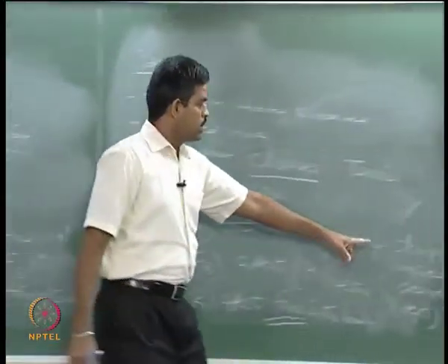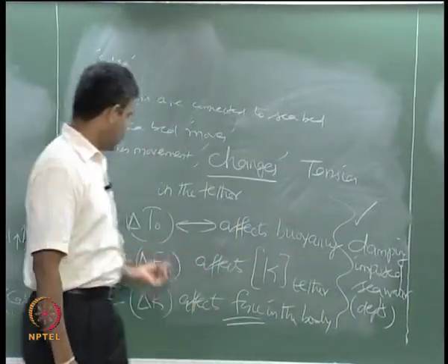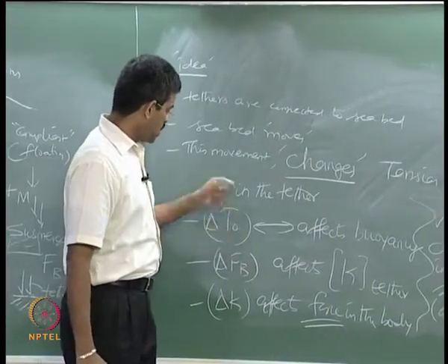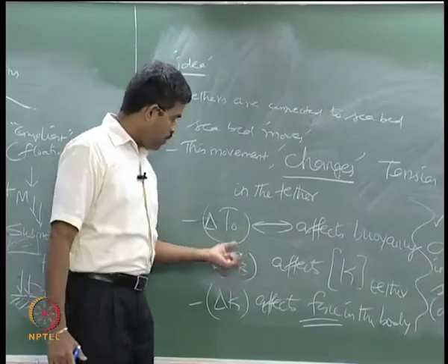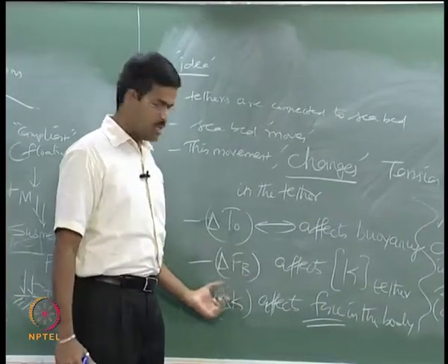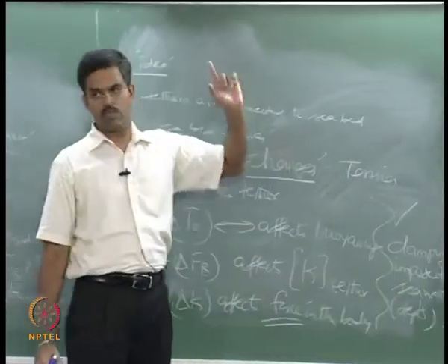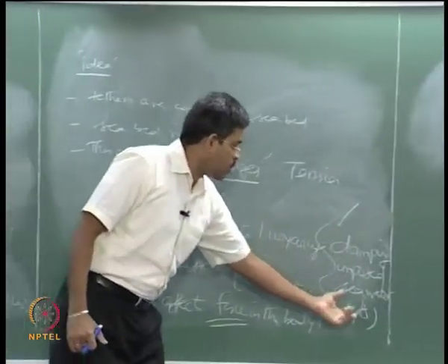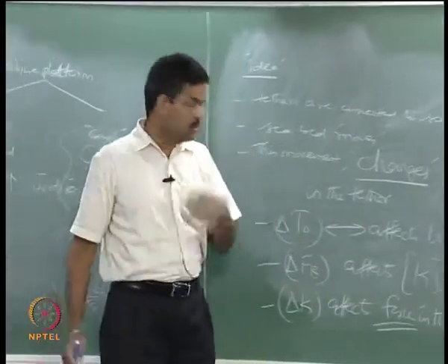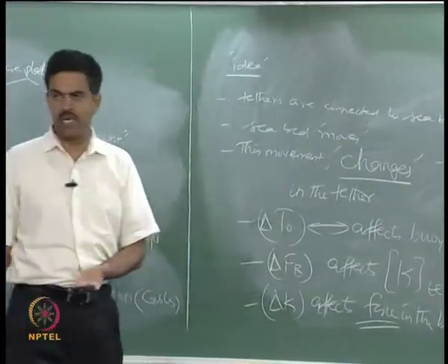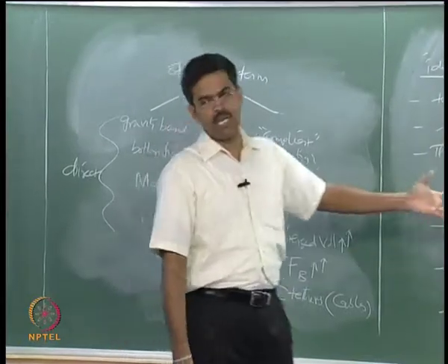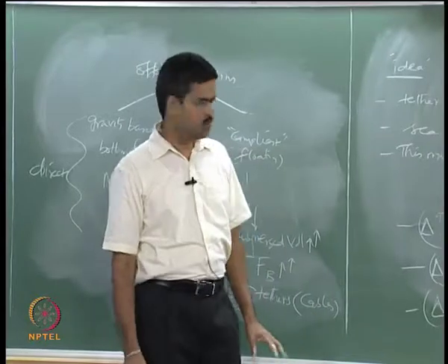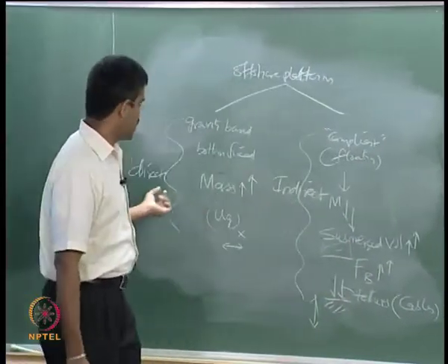The damping will reduce the forces on delta T naught, and that will counter affect the buoyancy, and the buoyancy will counter affect stiffness, and stiffness will counter affect the force on the superstructure or on the deck. So the damping imposed by the water depth on the floating system because of earthquake action happening in the seabed will be automatically accounted in this mechanism. So it is an indirect method, whereas this is a direct scheme.